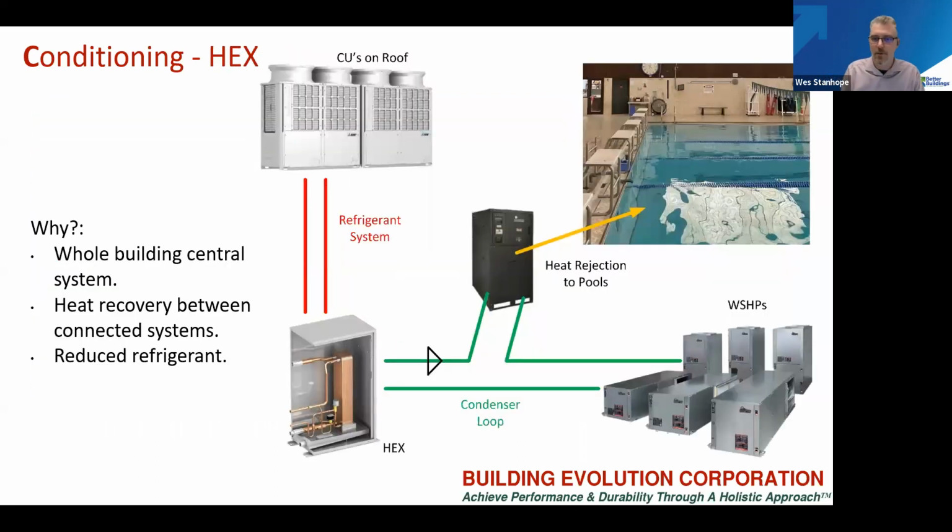But if you go to the next slide, we've had Mitsubishi work with us on developing HEX and bring that to the market, where you have the VRF to heat exchangers that use hydronic to go into existing buildings with condenser loops. It allows whole buildings to have heat recovery, and that heat could actually go to other sources such as heating pools for YMCA projects or other buildings. And it allows for larger buildings or historical buildings to have larger systems that VRF could not actually work in for electrification.